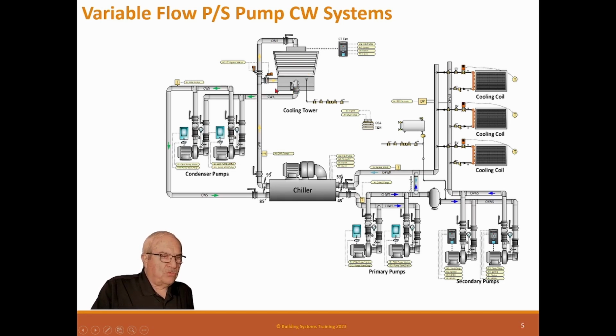Now, will it work? Sure, it'll work, but you will never be able to balance between the two. So in other words, when you're in bypass, this whole system will see a different pressure profile, and you can't change it because you can't have both. You can only have one. So this is a system you can't balance. Is it terribly critical? No, it's just not right. So for the system to work best, it should be into the basin.